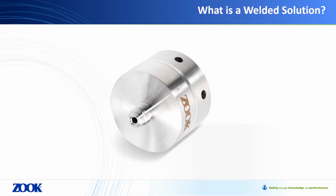We had mentioned that traditionally, most rupture discs are installed using compression of some type, usually generated by a clamp, companion flange, or other threaded methods. Welding is simply another tool in our toolbox to ensure that we can provide solutions to both unconventional installations and installations where stringent performance parameters are required.